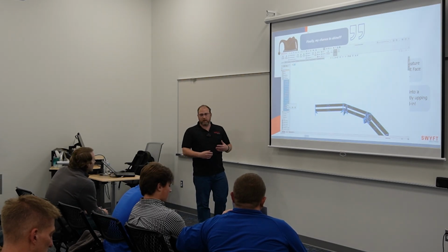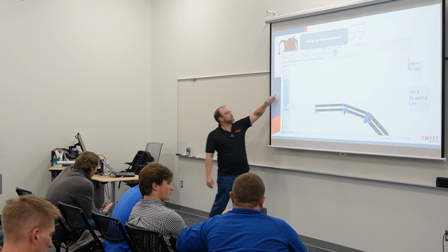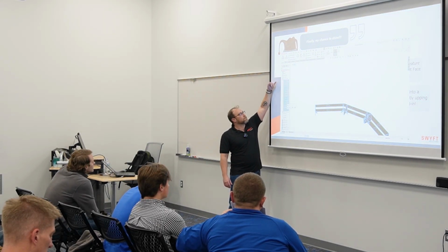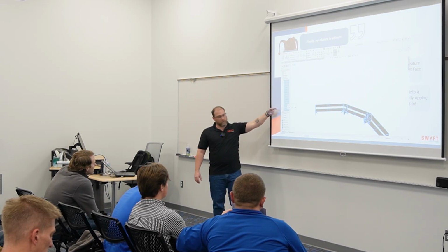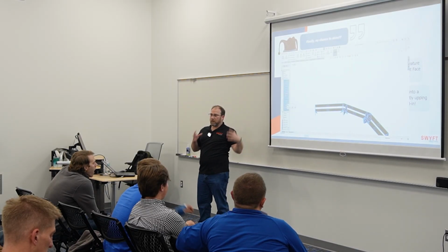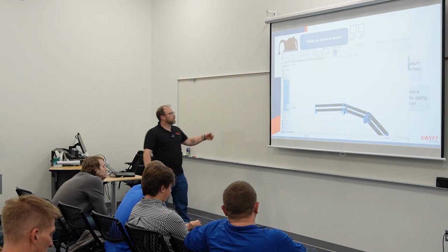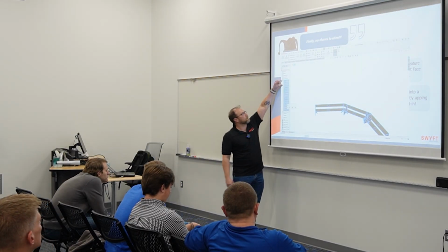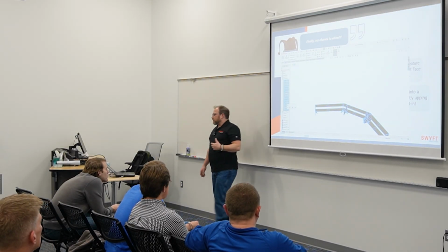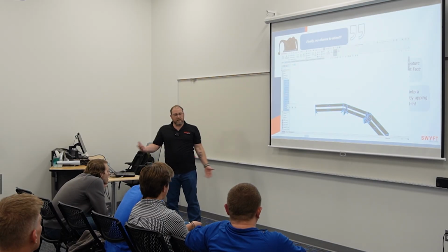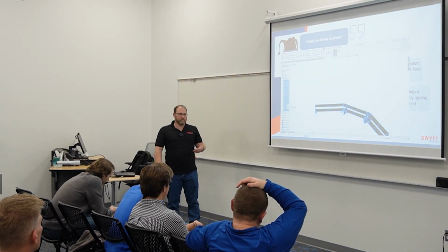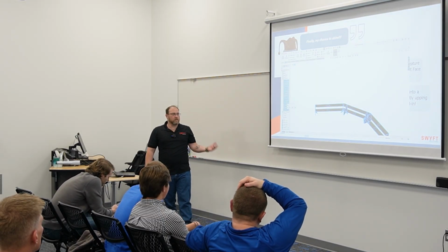If you have a multi-body part, you'll see the solid bodies folder appear, and in it, it will list any of your bodies. So if you had one sketch that had 3 circles and you extrude 3 cylinders, it would list 3 bodies right here for you. And there's some pretty cool stuff that you can do with this. It's basically going back to Boolean operations, and you're thinking it's 2025.